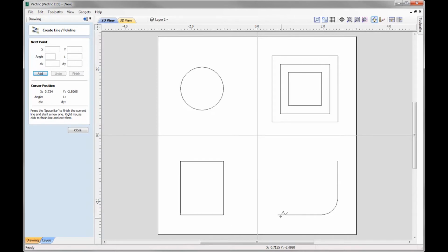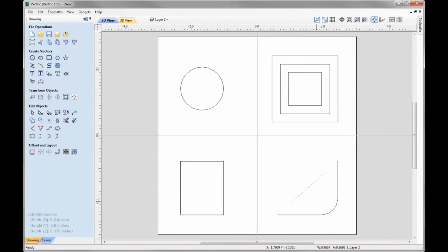For example, wake this point up, bring that along, and you can see that I can find the center of that line, or I could just connect anywhere between the two there, like so. Smart Snapping is a very powerful feature for us to create accurately aligned vectors very easily without the need to create construction geometry like you saw in this example.